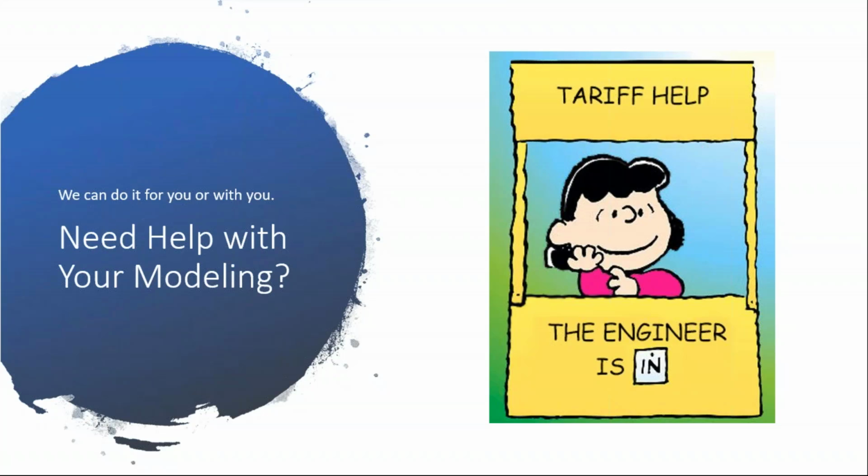Can you change the battery life calculations by cycles instead of throughput? We have an advanced storage module. If you go into our library and look for a battery with an ASM label attached to it, you can copy it and edit it, and it gives you an enormous amount of flexibility in changing the parameters, including the lifetime calculations. So we should have a whole seminar. I think we are going to have a webinar, but not next month, sometime in the future, just on our advanced storage module, which is quite sophisticated.